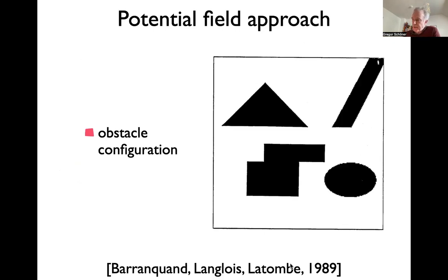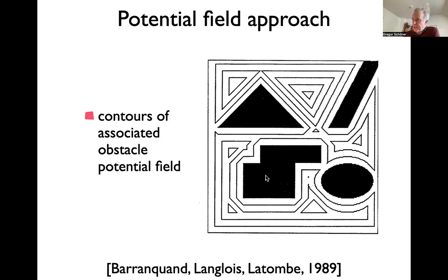Now, I'll show you an example that comes from the Thomas lab that is really classical planning with potential fields. So where you know the world, where you have a map of the world, in fact, polygonal worlds, and where it is finding the potential around that notion. So for instance, in that particular version, what you do is define a potential by defining equipotential lines mathematically, and essentially some distance function with a lot of ad hoc assumptions how to deal with corners and so on, that will take the polygons into account and then compute the potential with some rule from that. So for instance, you essentially determine the next equipotential line by some algorithm that looks at the distance from the different surfaces in 2D, so the different polygonal lines that delineate obstacles.